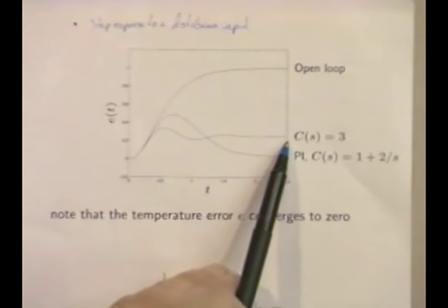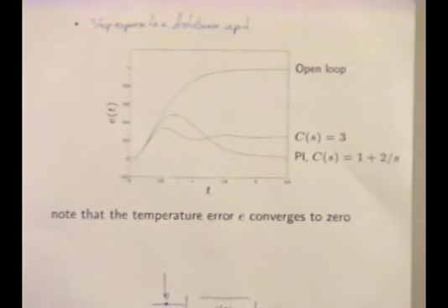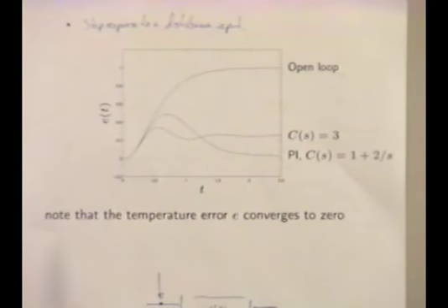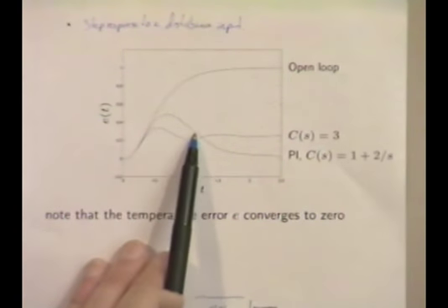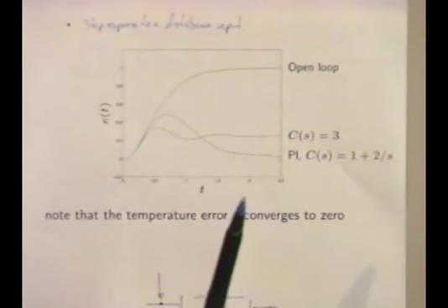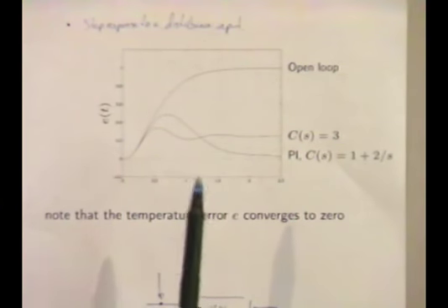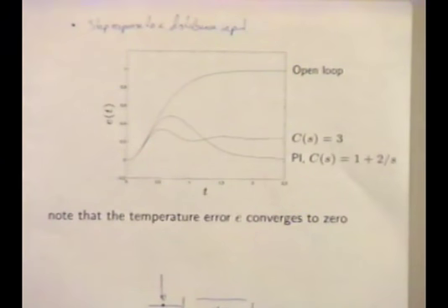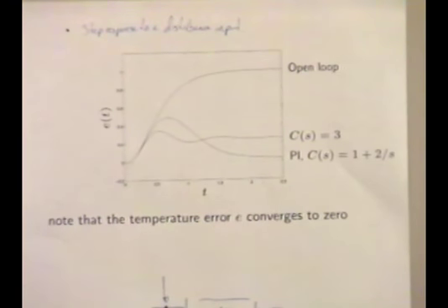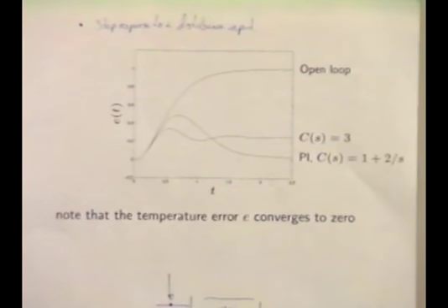And with the proportional plus integral term, from this example right now, you indeed get the desired steady state response of 0 to this disturbance. This is an exciting topic, and we're going to finish up this class next time, and I think it's time we go to our quiz.